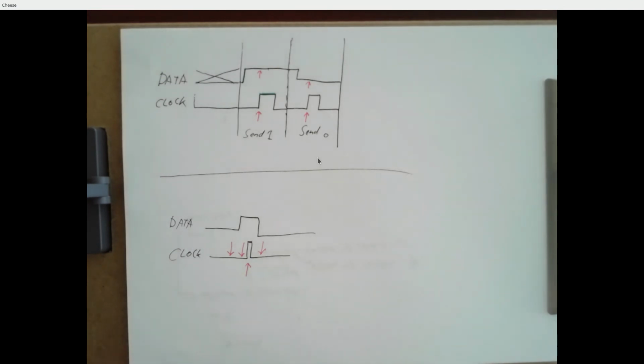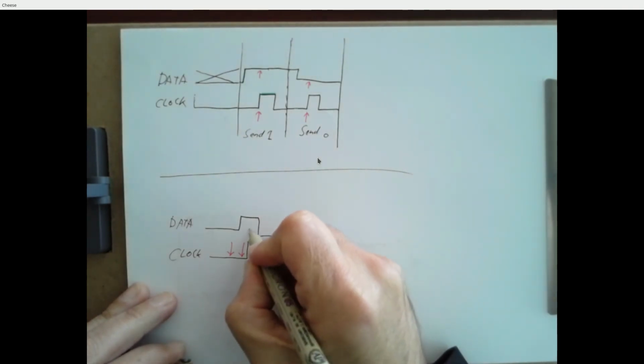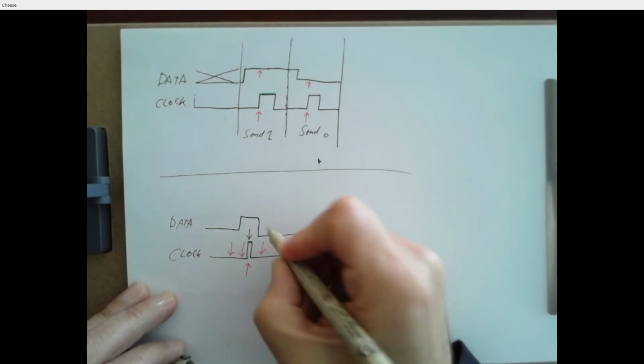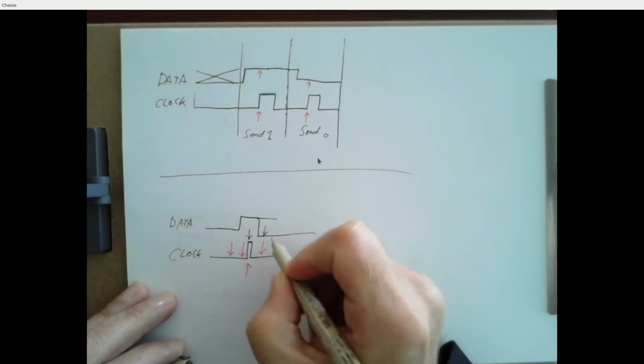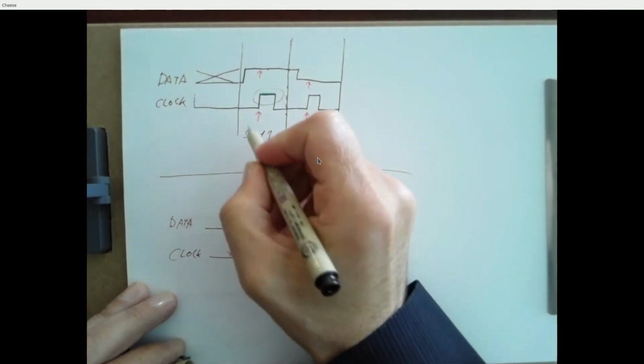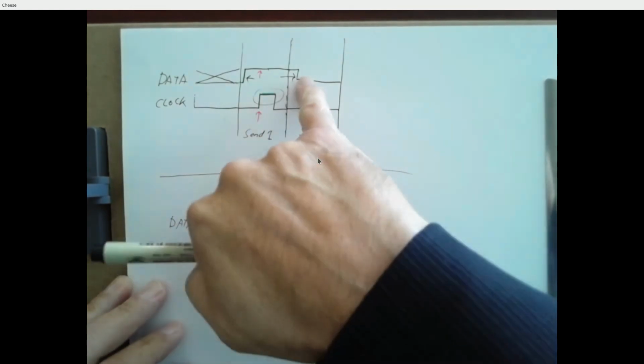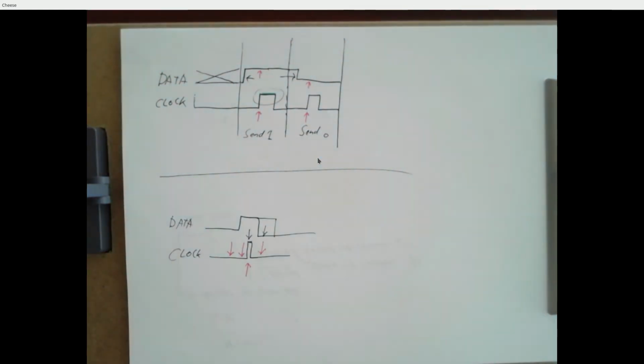And then similarly, there's a hold time after the clock to make sure that if you notice the clock right here, but you don't actually get around to reading the data until over here, you'd like to know that level is still correct. So this has got to be wide enough, this has got to come early enough, and it's got to change late enough. So that's typically setup time, hold time, and that's your pulse width. And start off making them generous, right? Put them in the millisecond range and you'll be fine. But if this clock is a millisecond, you're limited to 1,000 characters per second, pretty slow. But make it generous and then try to dial it in.